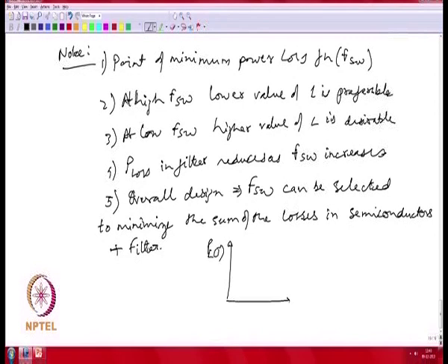as a function of what your L per unit is, and it is also a function of your switching frequency. Essentially you are looking at what is the point which gives you your best desired loss subject to constraints on your total value of L lying between some minimum and maximum range.